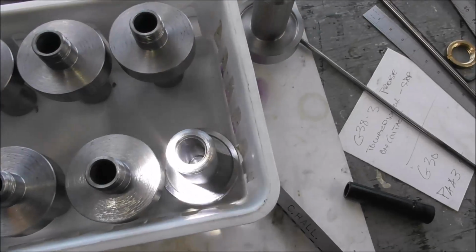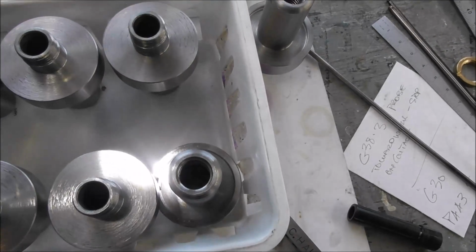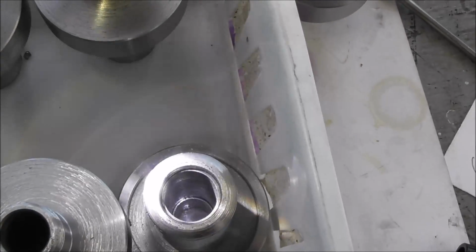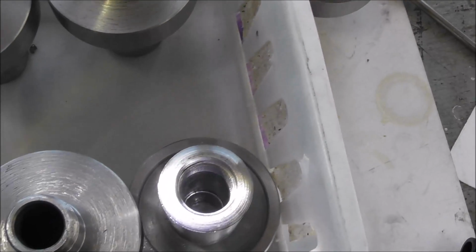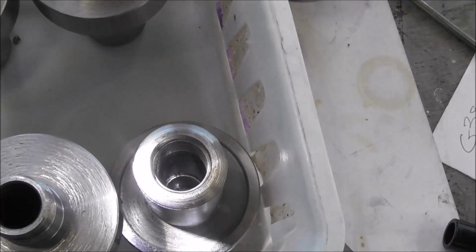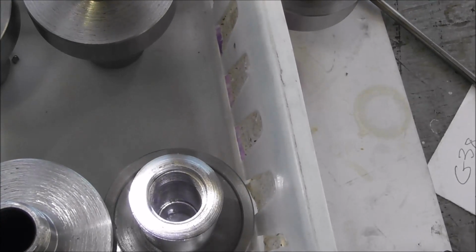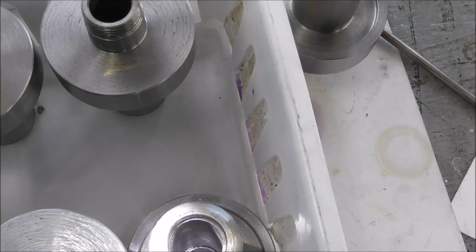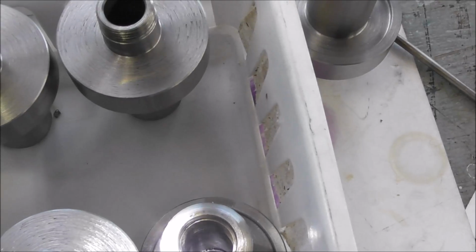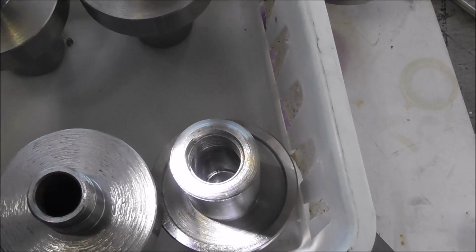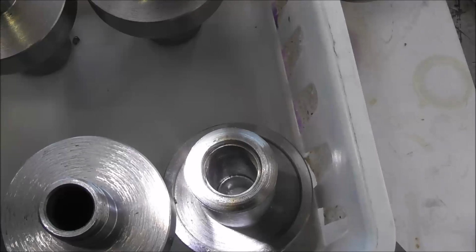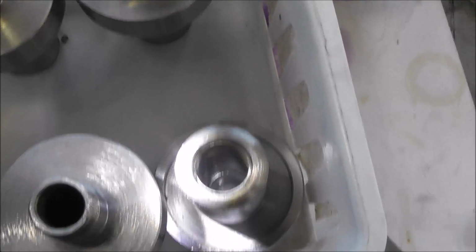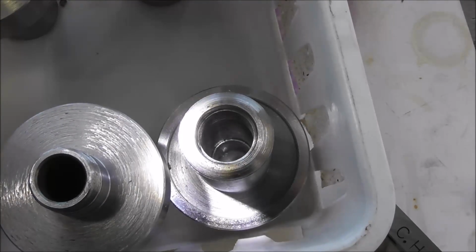With these ITTP arbors, there's two internal diameters. See if I can show it to you here. And there's a face down there, and that face is an end stop for the impact tolerant retract mechanism to contact. And it would be a nice refinement if that face was skimmed and undercut slightly. It would give an even bigger margin, design margin or factor of safety.